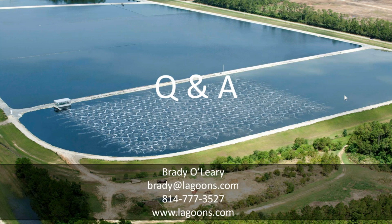They're like bacteria condominiums. The difficulty with putting fixed media in your lagoon is it's kind of a stagnant environment and it's hard to aerate it super well. Either you get rag buildup on it, which clogs up the media, or they become kind of redworm farms. So you get midge flies that lay red worms, and they eat the bacteria that grows on this. So there could be a kind of counterintuitive effect there.